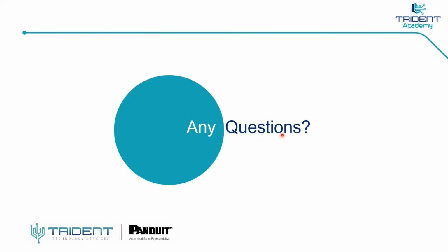Mr. Yasser Talat is asking if the DAC cables follow TIA or ISO standards, or do they have both? Yeah, the DAC cable is not a structured cable. It is a point-to-point solution to make connections from the servers to the switch at the top of the rack, or even from switch to switch over shorter distances. So it is not a structured cabling system to be approved by TIA or ISO. It is a cable related to the active equipment to make direct connections between active devices.